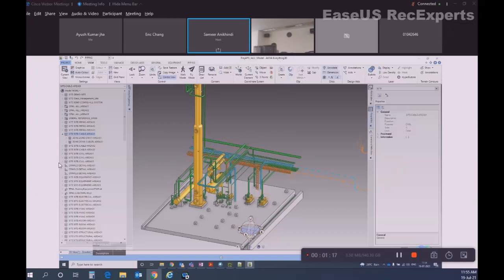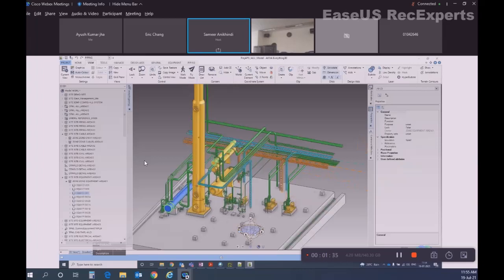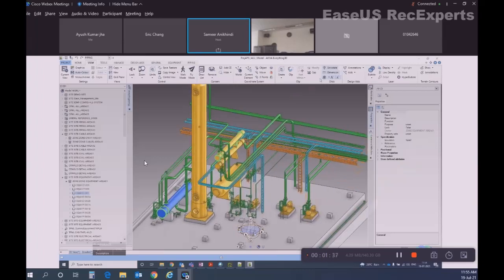From view, the clip menu over here, clip group, and inside that there are different options. So to begin with, you can start clipping. Say you are working on these two elements I've selected. I can clip a boundary around these two elements, and whatever is inside that boundary will be visible, outside the boundary will not be visible.